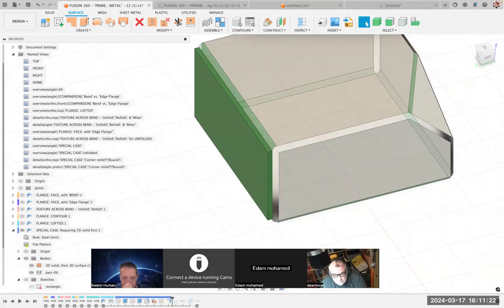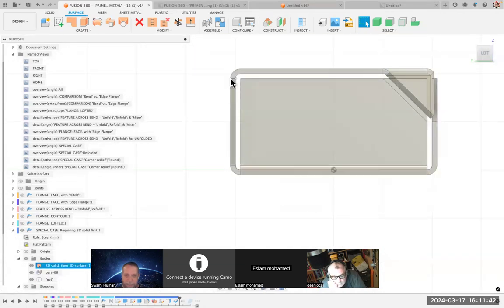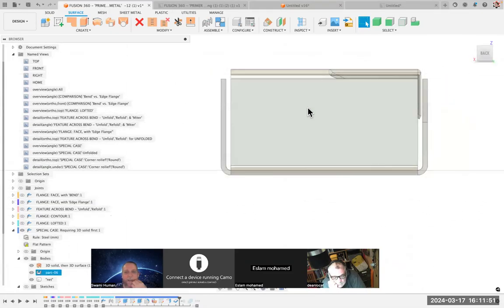We go forward one, and this is our thicken. Boom. So that surface went outward all the way on the outside, and now it's the 2.5 millimeters thick based on our rule for our sheet metal. And because I've done it correctly, that green one is perfectly where it needs to be on that face. And it's the perfect size because I projected in the geometry right there. So everything is the way we need it.